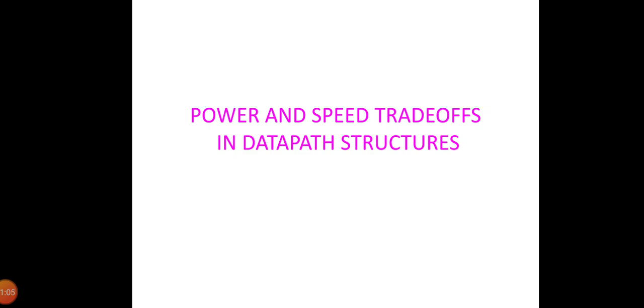The architectural optimization techniques that are available to the designer differ based on the design constraints. Pipelining or parallelization, for instance, works effectively for the throughput constraint scenario, but it may not be applicable to the latency constraint case. With the fixed architecture of the data path, speed, area, and power can be traded off through the choice of the power supply voltages, transistor threshold, and device sizes. So, this opens the door for a large variety of power minimization techniques. And now let us see one by one.